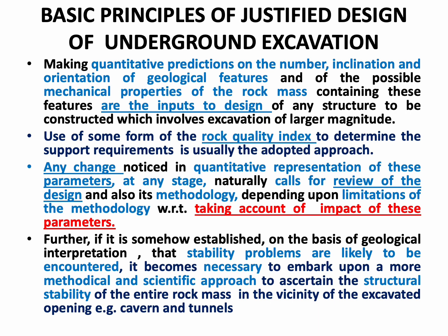when there is any change noticed in the quantitative representation of these parameters based on which the initial design was done, it calls for a review of the design and its methodology depending upon the limitations of the methodology. Further, if it is somehow established on the basis of the geological interpretation that stability problems are likely to be encountered, it becomes necessary to embark upon a more methodical and scientific approach to ascertain the structural stability of the entire rock mass in the vicinity of the excavated opening, that is cavern and tunnels.